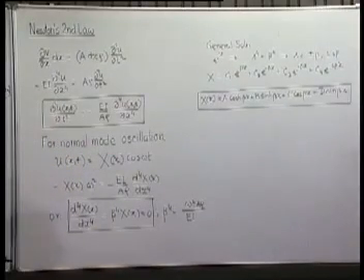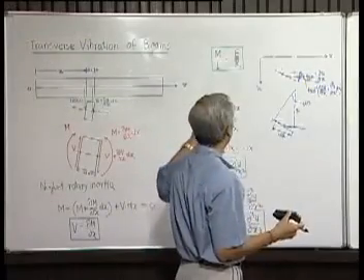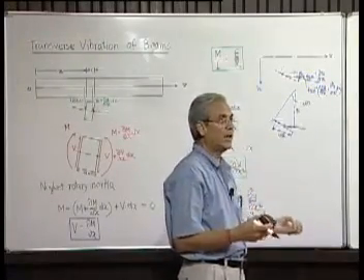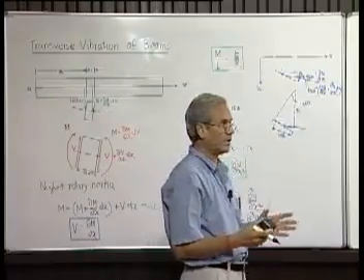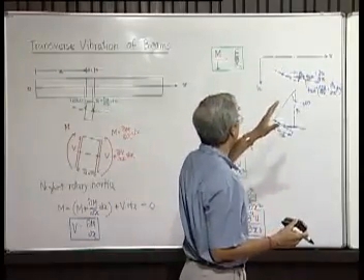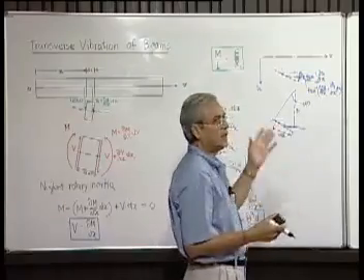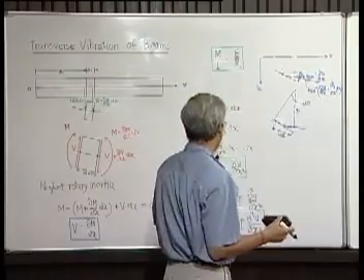In the case of a beam, the boundary conditions will be 4 in number, 2 at each end. At each end you have to specify either the deflection and the slope, so there will be 2 conditions. Or, in the case where the end is free, the shear force will be 0 and the bending moment will be 0.